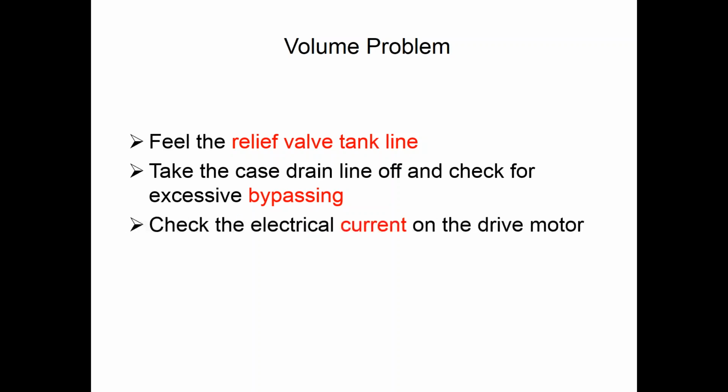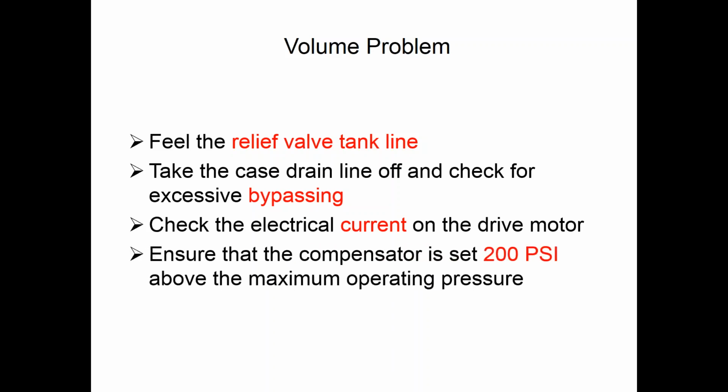Check the current on the drive motor. Again, it takes more current to turn a brand new pump than it does to turn a worn out pump. But of course, check the minimum and the maximum current draw. Make sure that the compensator is in fact set at least 200 psi above the maximum operating pressure.